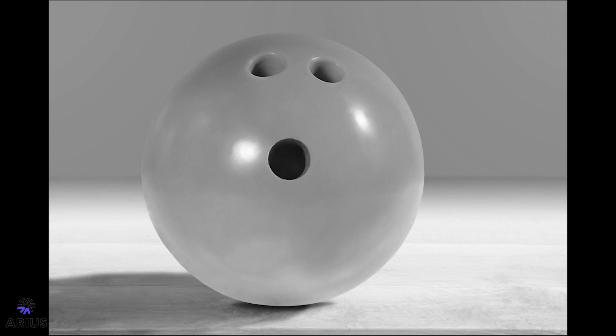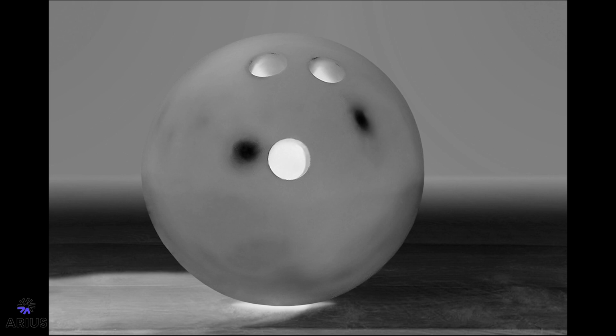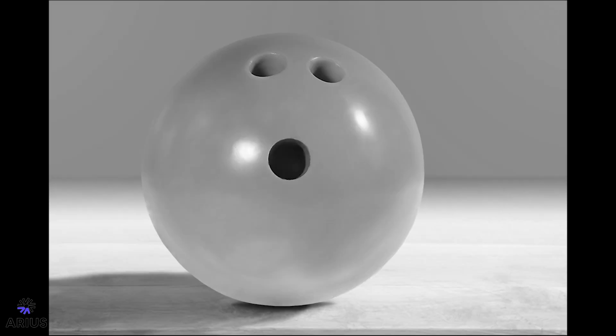In some cases, inverting the grayscale image will fix the problem. So in this case, inverting the image will turn the dark finger holes white, which is the beginning of what we want, but then the white highlights go black and we want a spike again. This can be avoided by cloning out the white highlights in the grayscale image, but no need to adjust the original color image. In this case, some editing is required to make these holes work effectively.